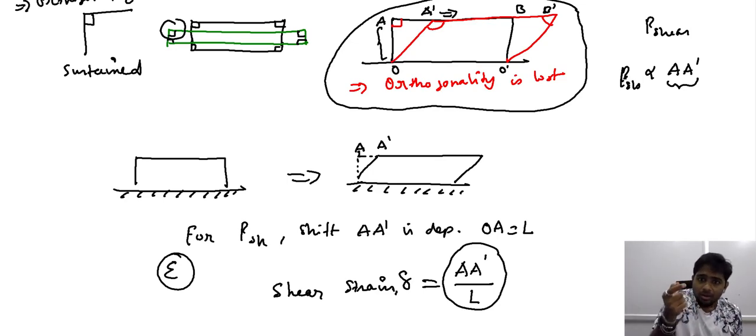Now, the description of shear strain that we have arrived at here is based on the shift in the corners. So two ways of describing the response offered by the material: one is shift in the corners, the other is the loss of orthogonality. So it is possible for us to arrive at the description that is based on the loss of orthogonality, that is the change in angle from 90 degrees, the perpendicular sides now being no longer perpendicular.